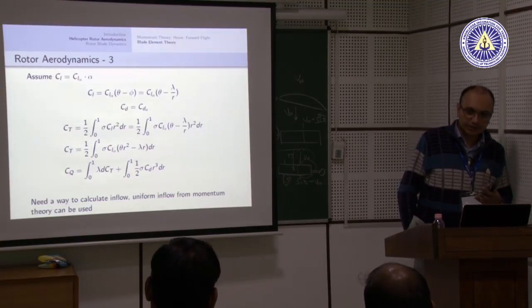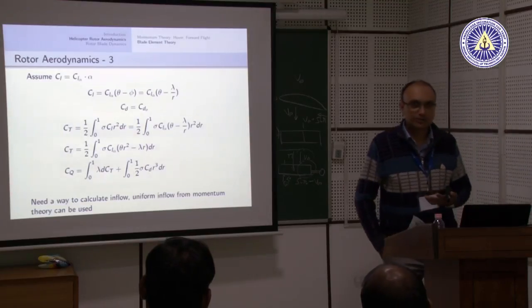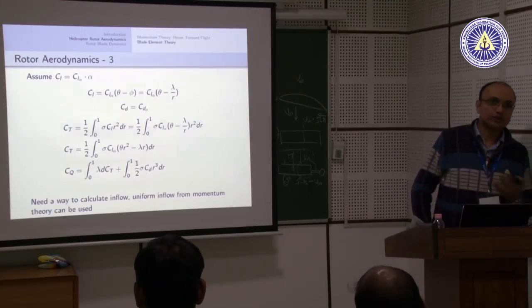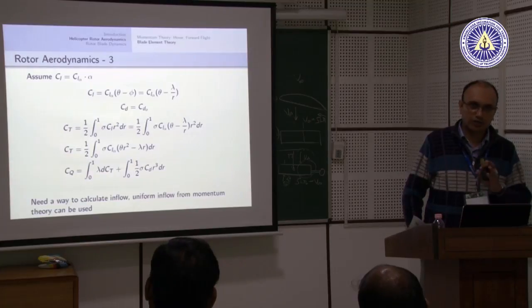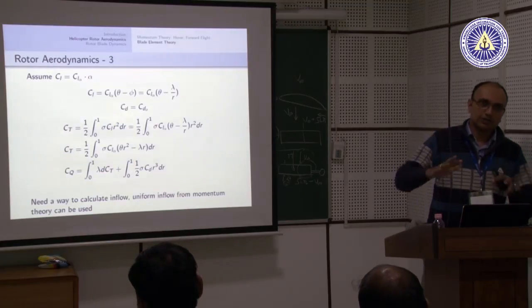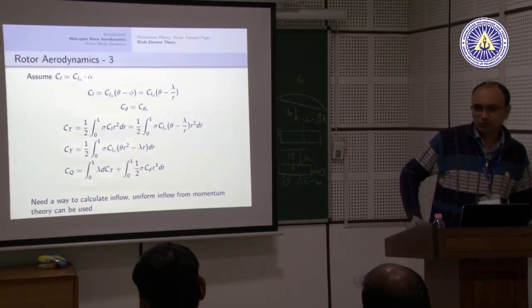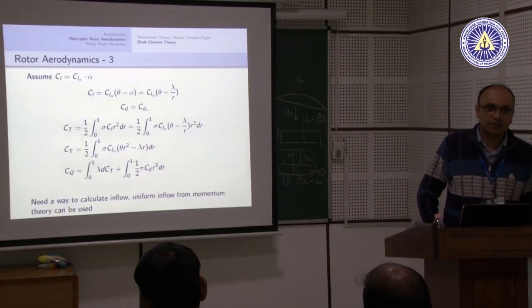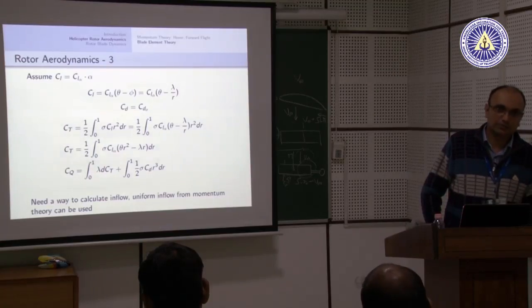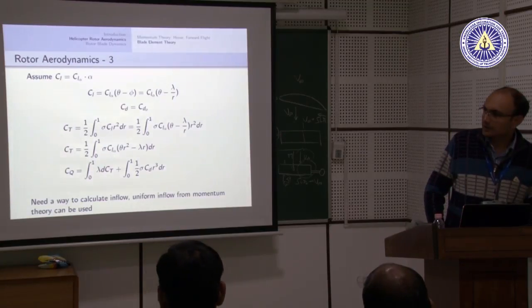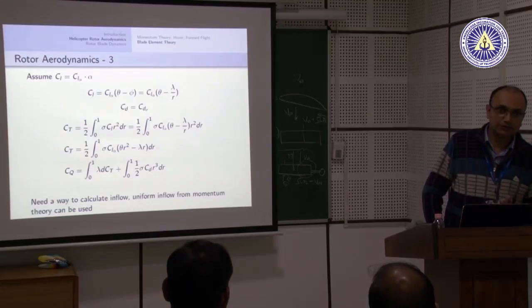So solidity is a design parameter which impacts the design more than the control. For control you do not have to worry about solidity, because you know what rotor you are designing the controller for. It is important for a designer, because it directly controls the amount of blade area.